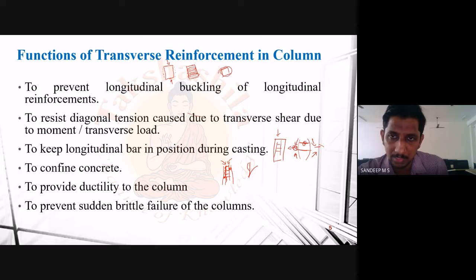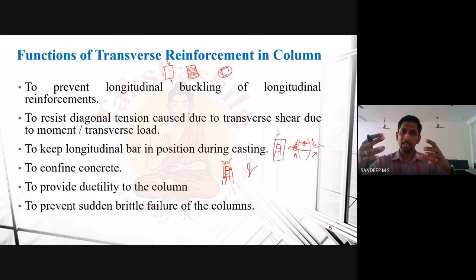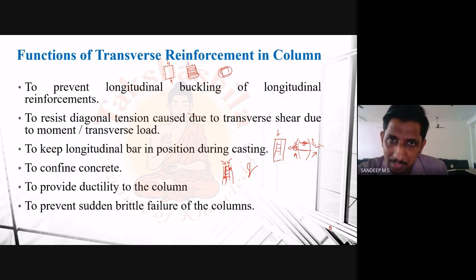What it is actually doing is confining the material inside. That is, the rubber is confined by tying it using this twine. Now if I am applying the same load, will it have a behavior like this? No, it will not. It will be much more stable.